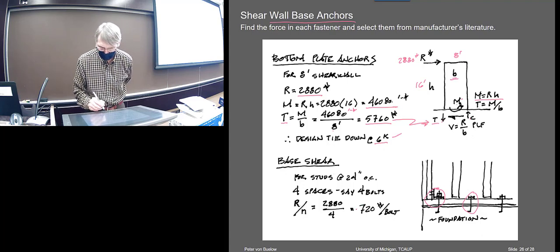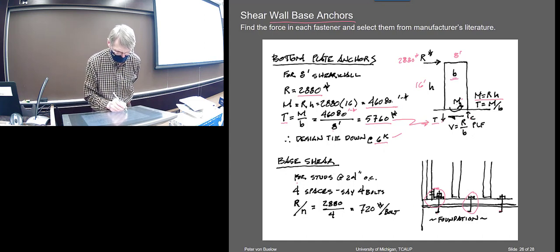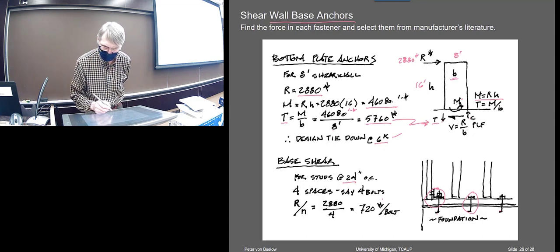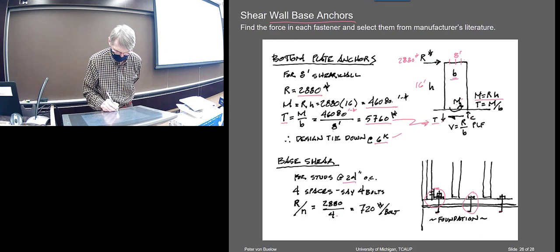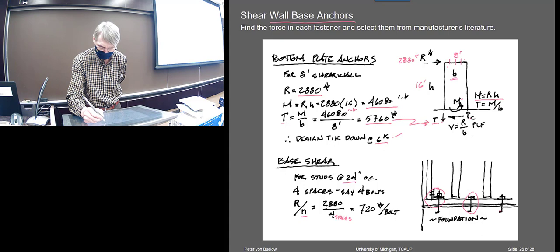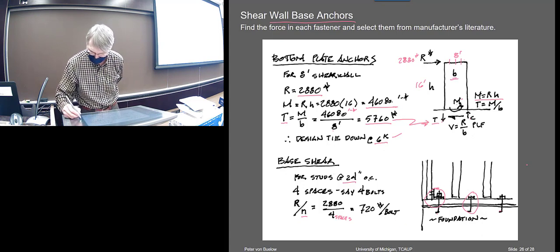Okay, the base shear of these guys, you just need a shear force. So we've got the studs at 24 inches on center, and there are 8 of them, right? So what do we got? That would be 4 foot. I got 1, 2, 3, 4 spaces. So that's where that's coming from, spaces. And there are 4 of the bolts, right? That's the number of bolts that's being held down there. These bolts. One more than I showed there. I got one more.